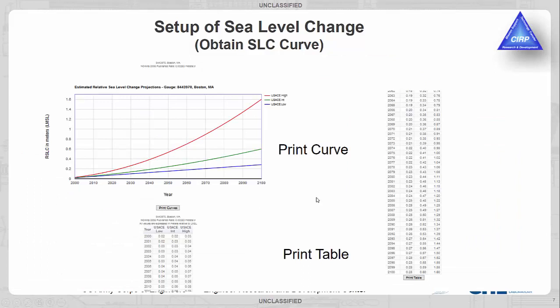And after you pick the site, specify the time period. So I specify 100 years here, from 2000 to 2100. So, 100-year sea level rise. I pick the USACE projection from the USACE formula and the sea level change. And then I see the low rise, intermediate, and also high. So you see 3 curves here.